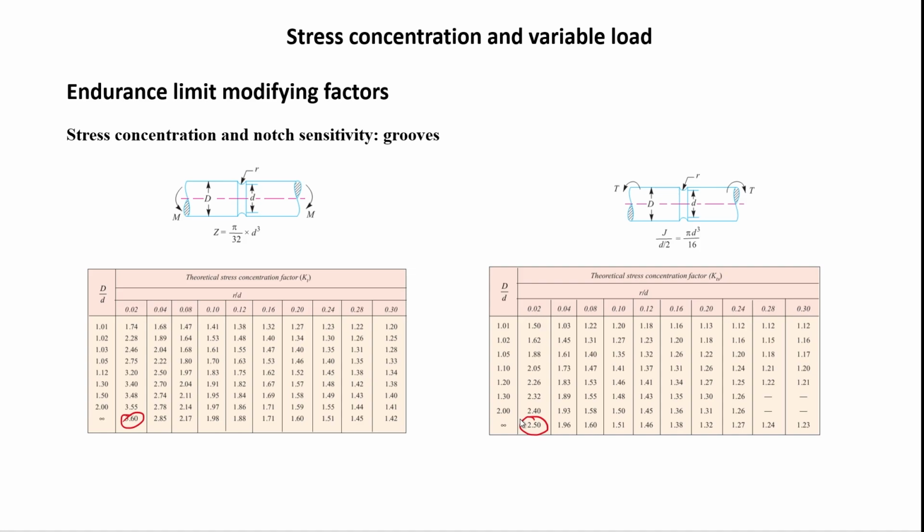So, seeing back when we were talking about this beam, we were designing in the exercise sessions last time, the profile I chose in that example resulted in a safety factor of 1.2 when you compare the section modulus of the selected beam against the beam that you should be using there. Well, 1.2 is a nice safety factor, but now if you're going to have stress concentration factors that ramp up your localized stresses by 4, then a 1.2 safety factor doesn't make sense to be using there.